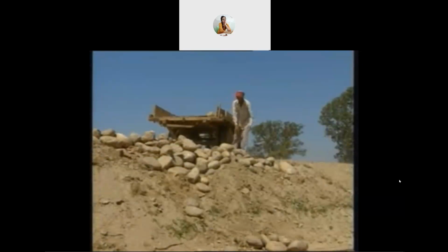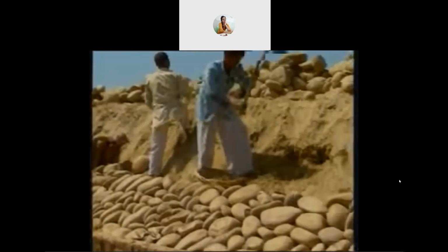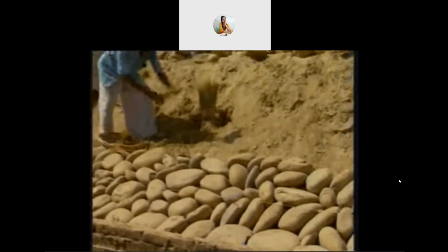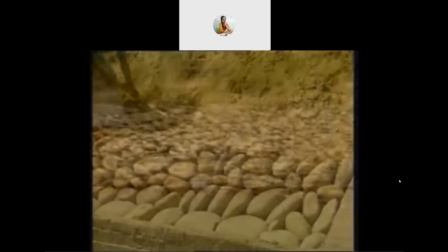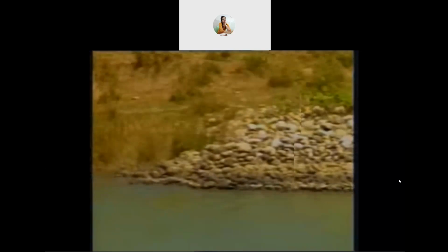Boulder lining is another economical lining where boulders obtained during excavation are readily available. It has very little flexural resistance or flexibility. Such lining is not satisfactory for canal infilling. Brick lining has been extensively used. It has the advantage of low initial and maintenance costs and construction.